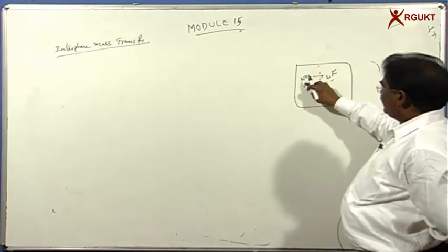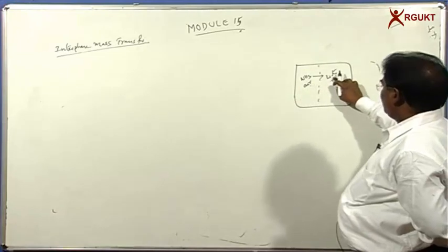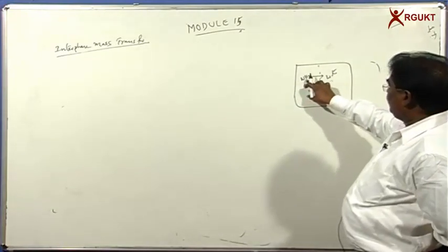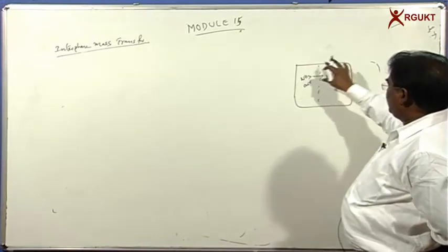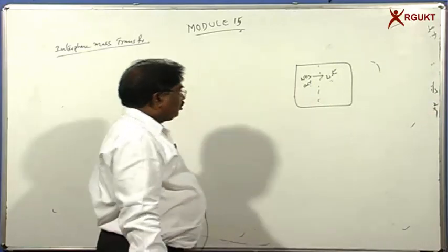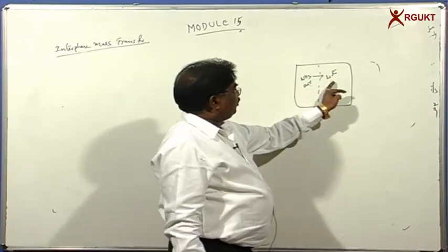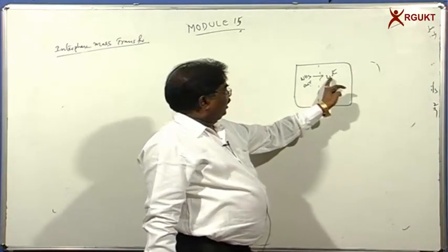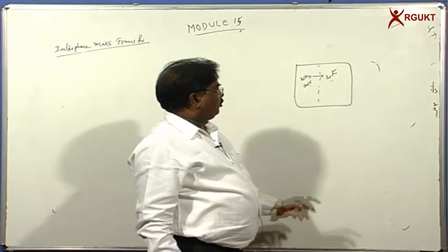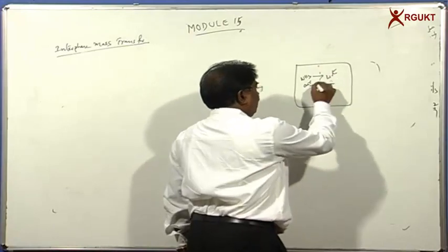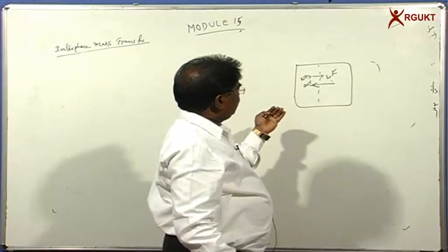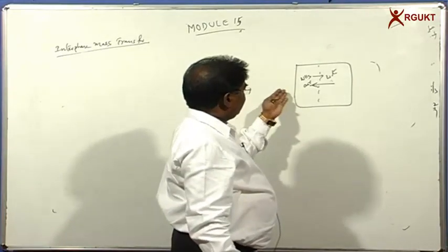The gas phase contains ammonia and air, which is contacted with the water. When it is contacted with the water, now what will happen? The ammonia will be transferring from the ammonia-air layer into the water layer. So when the ammonia is transferring into the water layer, the concentration of ammonia in the water layer is going to be increasing. When the concentration of ammonia in the water layer increases, in the backward direction some ammonia is returning back into the air.